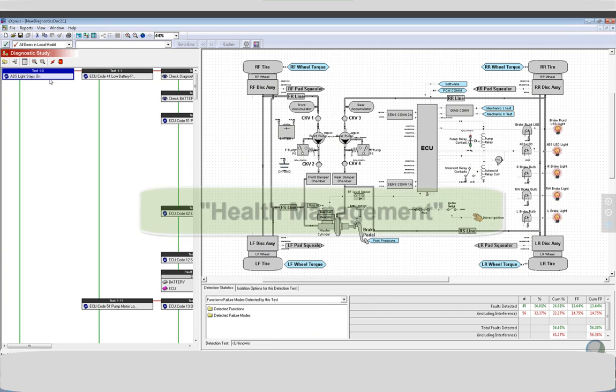If, on the other hand, we're dealing with a health management type paradigm, where we're getting snapshots of different sensors or fault codes at any particular time, we can think of this as a fault signature lookup table, where we have a series of failed tests or fault codes that are being produced by, for example, out-of-scope sensor readings, and we're using this as a way to take that set and determine the associated failures. It's like a checklist for being able to determine what these tests mean.